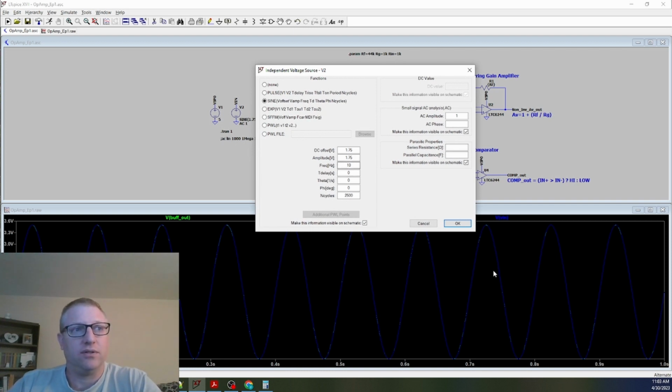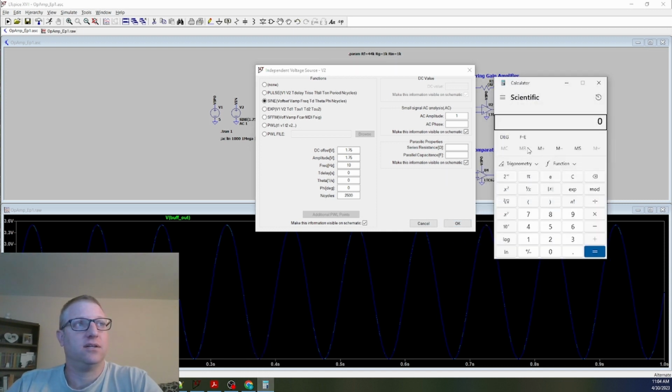So we know that our signal goes from 0 to 3.5 volts in one swing. So we need to get 35 volts per microsecond. Right? So how do we do that? Well, we have a 3.5 volt signal that we're putting into the system from low to high, and we have to get 35 volts per microsecond, so we divide 3.5 by 35 volts per microsecond, and that gives us 0.1 microseconds. So we need a transition of 3.5 volts in 0.1 microseconds.